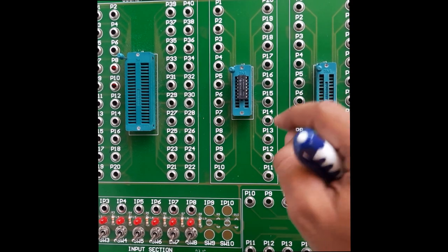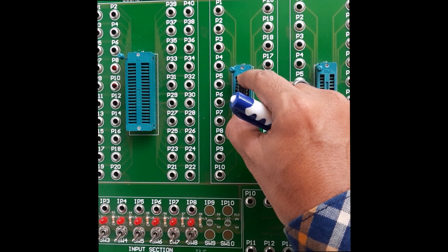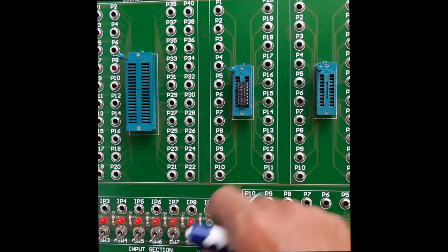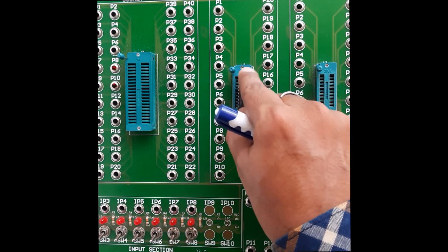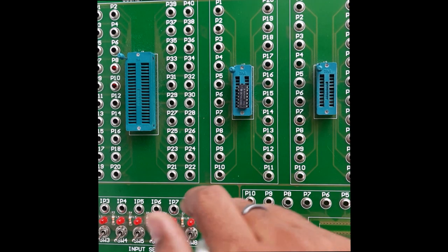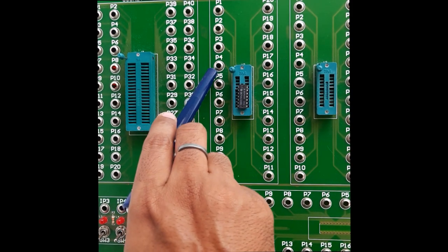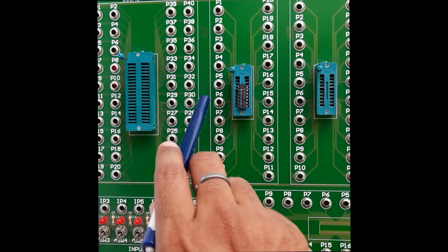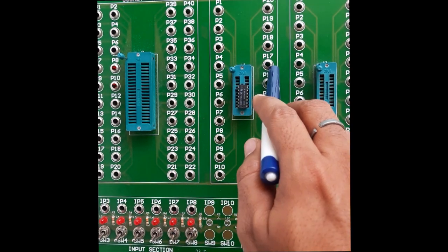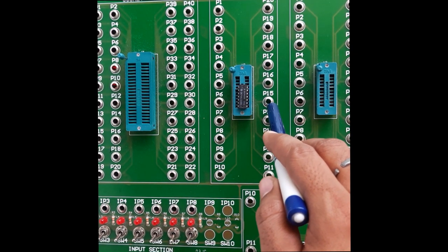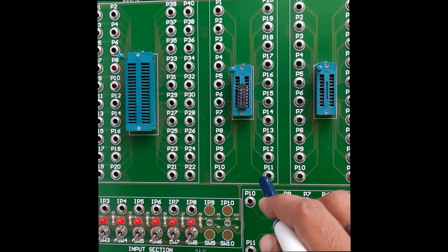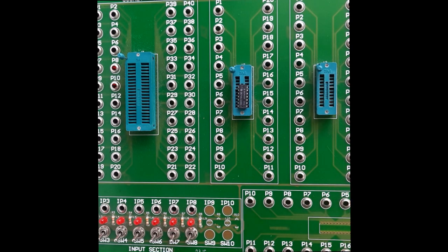You should understand the next thing: if you do not mount this IC properly in the first slot, suppose I have mounted this IC from the bottom side. It means that this pin is my pin 7 and this pin is 8. So first we need to calculate. This is my first pin. Now second, third, fourth, fifth, sixth and 7. In this way, if this is 1, then the other end should be 14. So 14, 13, 12, 11, 10, 9 and 8. In this way you need to calculate your pins.